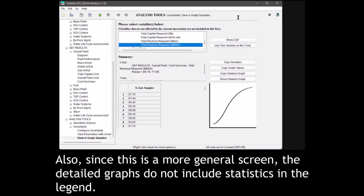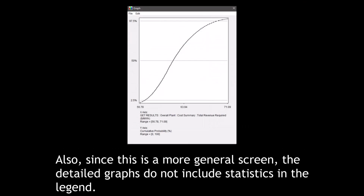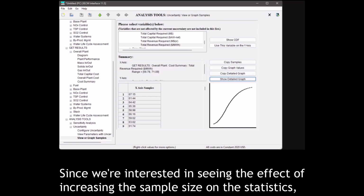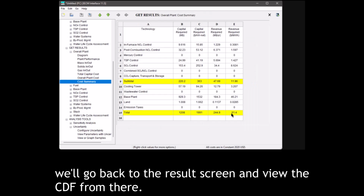Also, since this is a more general screen, the detailed graphs do not include statistics in the legend. Statistics are only shown when viewing or copying a graph from the right-click menu. Since we're interested in seeing the effect of increasing the sample size on the statistics, we'll go back to the results screen and view the CDF from there.